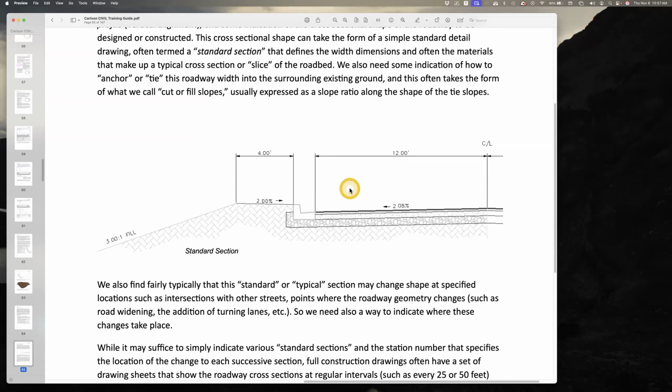If I've got 10 yards of cut in this location, but I go 25 feet away and I've only got 5 yards of cut, but I've got 5 yards of fill that I have to come up with, then on the average, I've got 7.5 yards of cut across that 25-foot distance. Okay, or if I did that mental math correct. I'm not here to see how mentally agile I can be, but anyway, you get the concept. So that's called the average end area method.